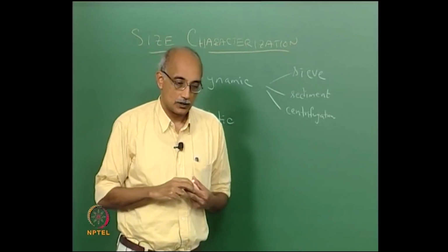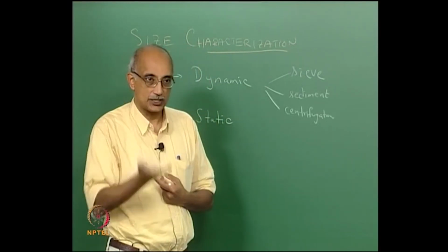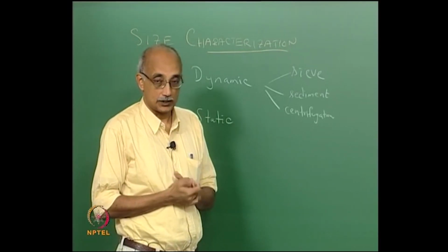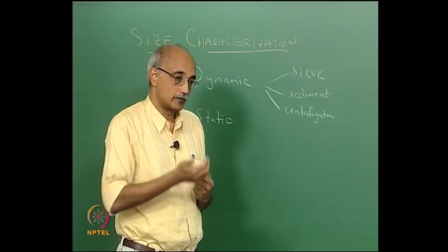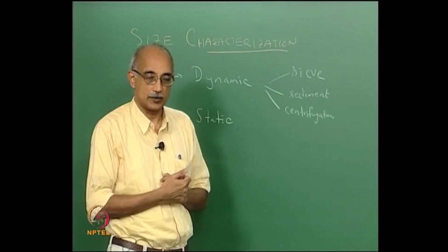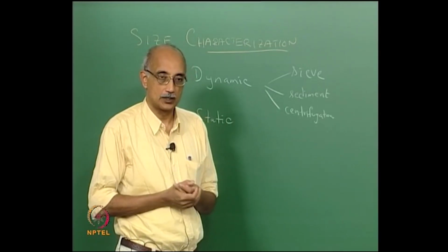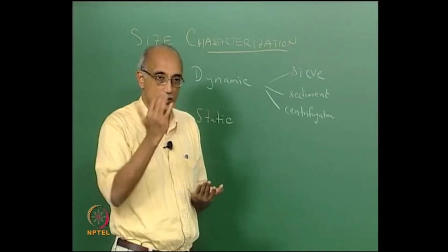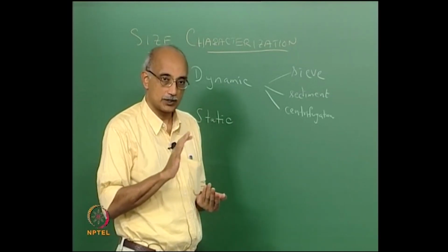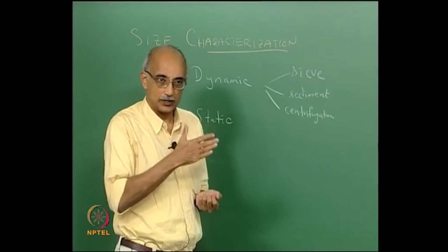For example, in sieve analysis, how do you measure size? You basically take a set of sieves with different mesh sizes and you put the coarsest mesh at the top and then put the finest mesh at the bottom, and you have a collector plate below the finest mesh, and then you take this particle powder whose size distribution you are trying to characterize, put it into the top sieve, have some kind of a sieve shaker arrangement which is designed to give very abrupt but at the same time very reproducible movements to this stack, and then you essentially vibrate the whole stack, right.